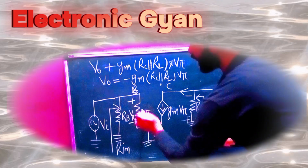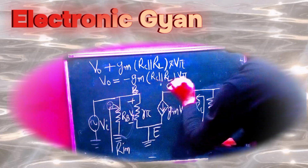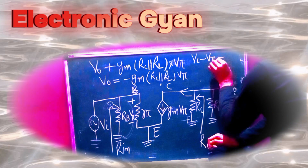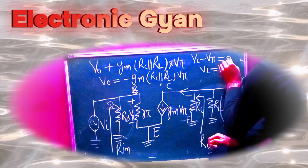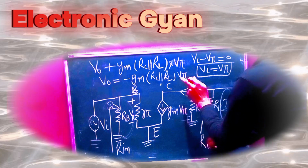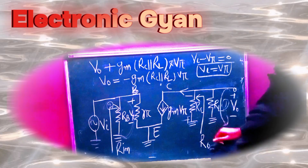Now by applying the KVL at the input side, in loop 2, what we will get here? Vi minus V pi is equal to 0. So if you see here, Vi is equal to V pi. Now I will put this V pi into this output voltage, so therefore I will get the voltage gain.